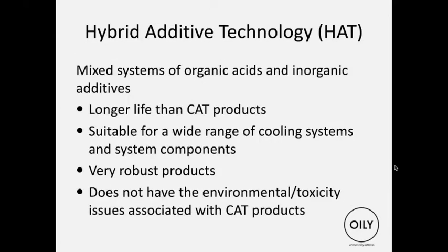And then the hybrid is a mixed system of organic acids and inorganic additives, longer life than the conventional products, suitable for a wide range of cooling systems. They're pretty robust, and it doesn't have the toxicity and environmental issues of the conventional products. Just be very aware that the glycols used in antifreezes are toxic, they're lethal to humans.